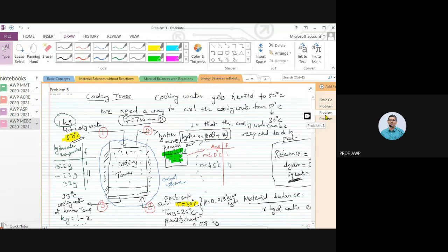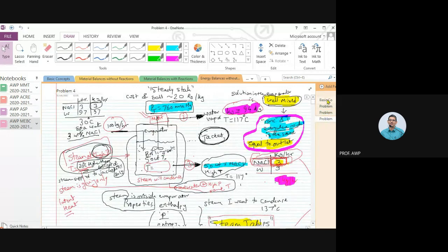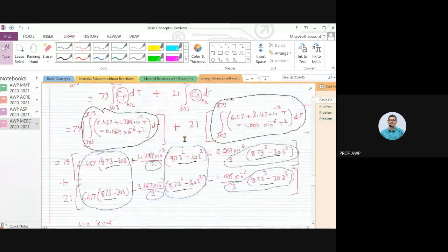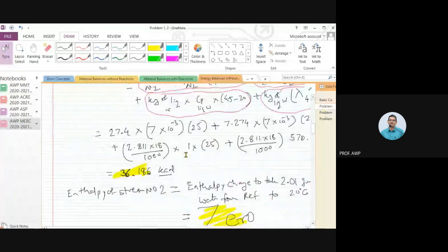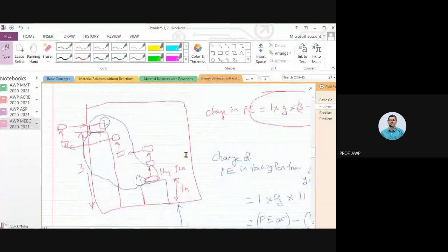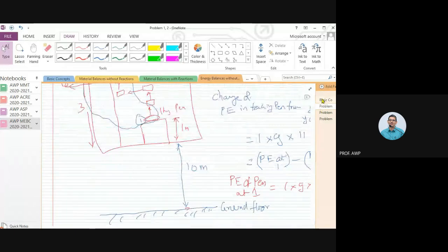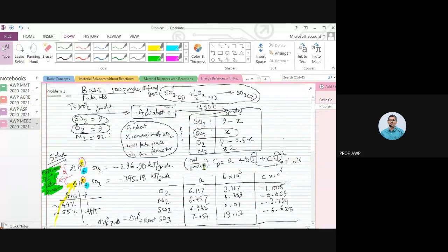Let me show that dryer problem. Wherever that dryer problem is there, we could effectively take any reference condition, because there was no reaction happening. Nothing was getting converted. It was only changing from one stream to another stream. But now that reaction is happening, some of these molecules have disappeared. Do you understand the difference between enthalpy balances without reaction and with reaction? Yes, sir.